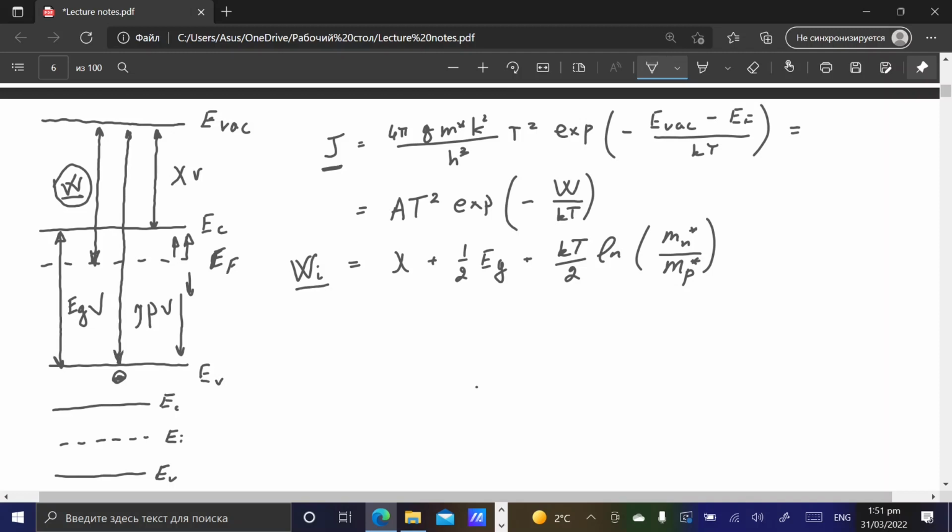So obviously we deal quite often with doped semiconductors, so in that case the work function of an n-type semiconductor can be expressed as the affinity of electron, meaning this gap, plus the depth of the Fermi energy location with respect to the bottom of the conduction band.